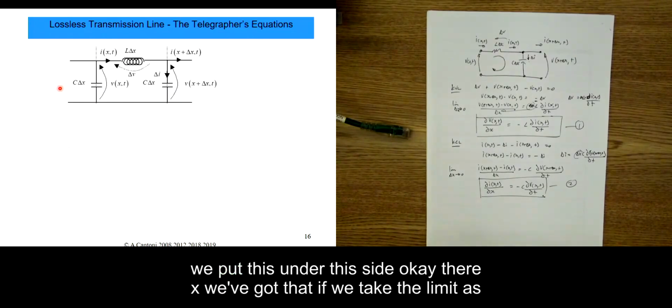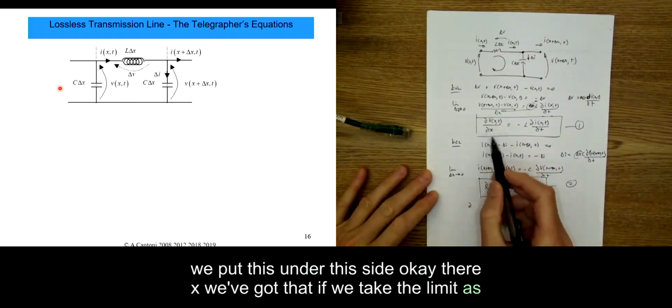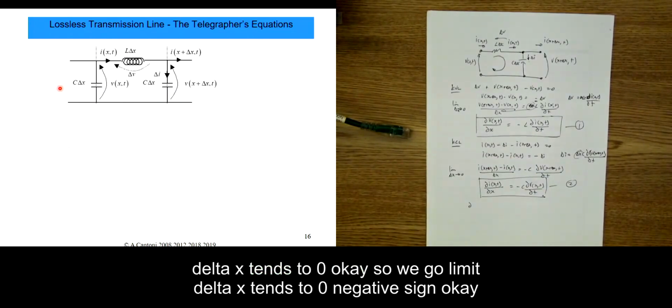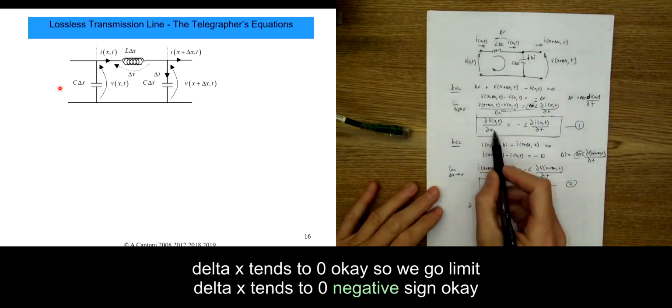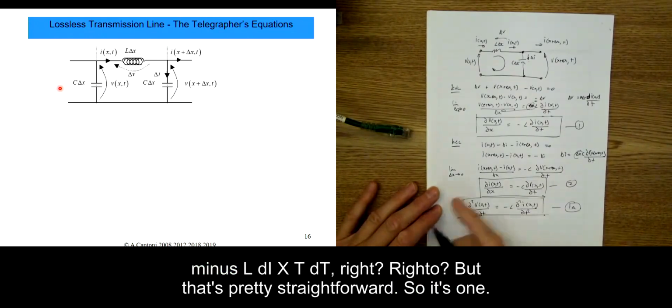If we divide this side by delta x, we've got that. And if we take the limit as delta x tends to 0, with the negative sign, that's going to be partial V(x,t) over partial x equals minus L partial I(x,t) over partial t. That's pretty straightforward. So that's one.